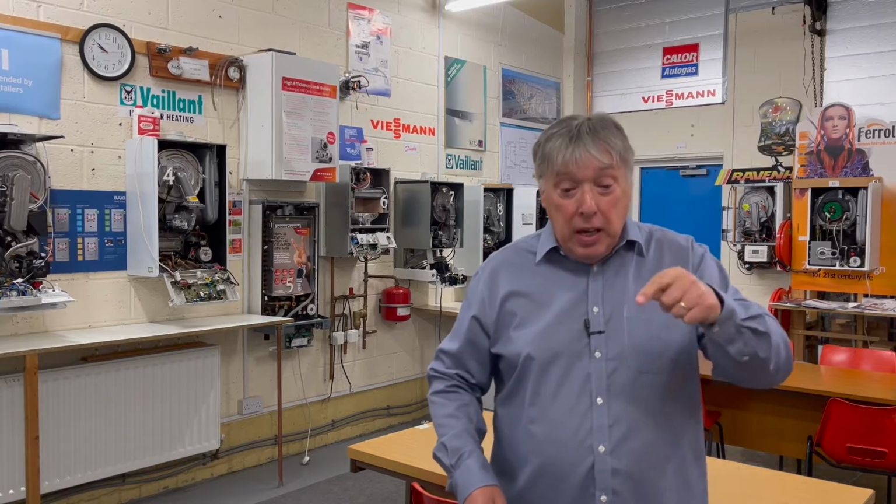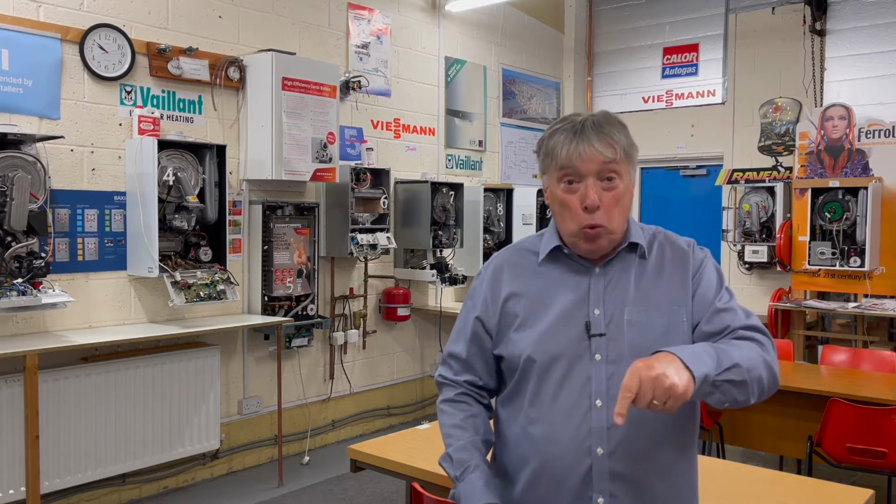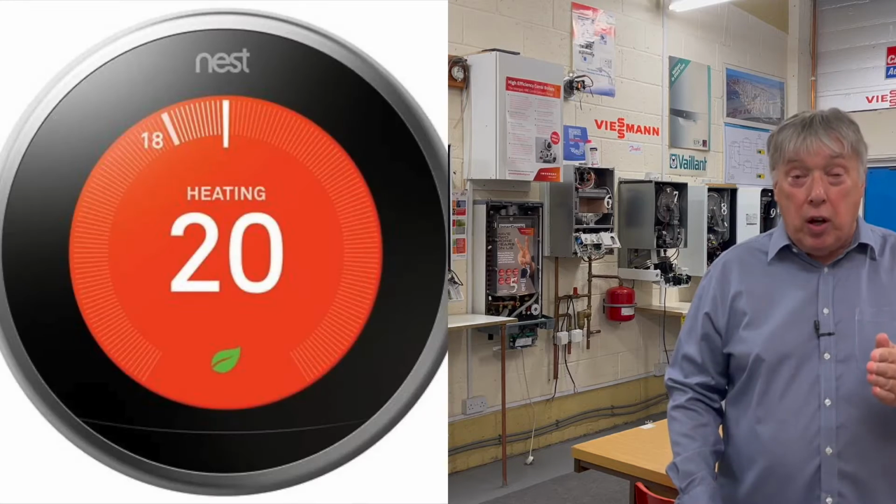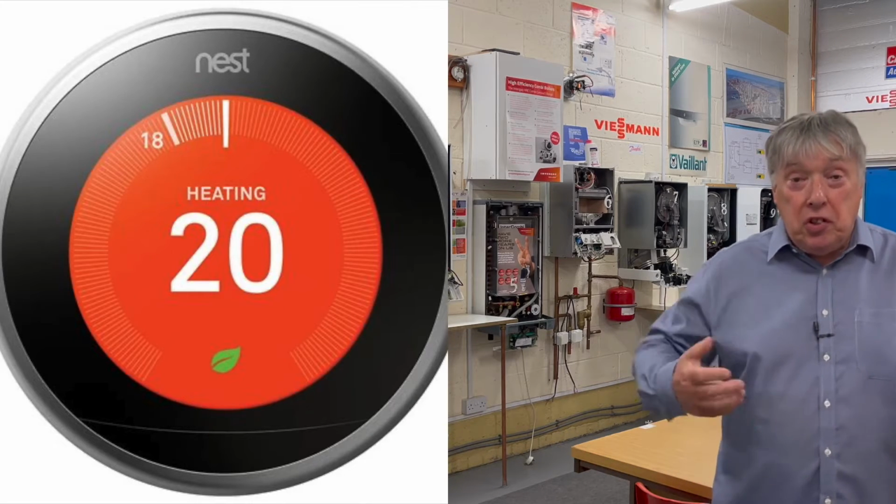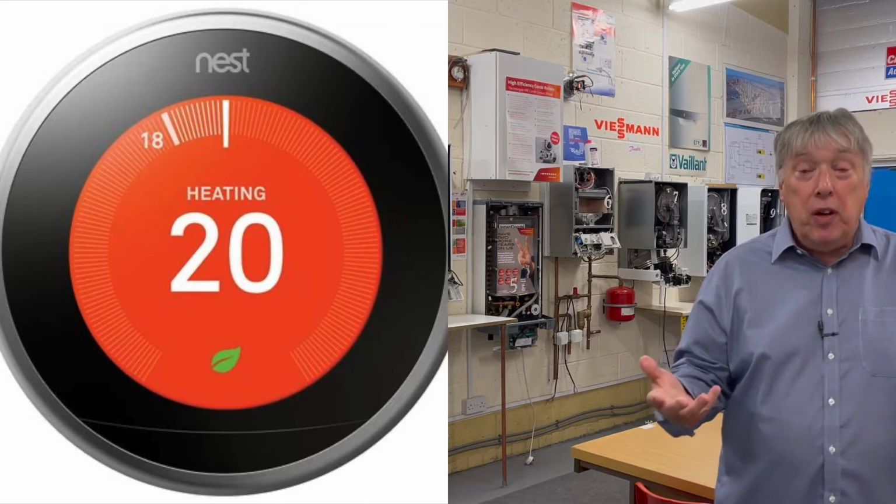house. To an installer, heat loss means how large a radiator has to be fitted in that particular room to take it to a temperature of 20, sometimes 22, but the 20 is the general figure for a lounge for people to sit down and watch TV.